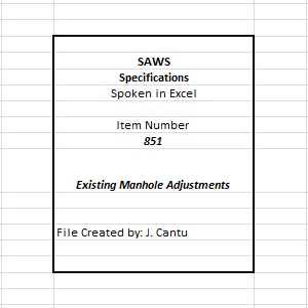16. At the direction of the inspector, all ungasketed mating surfaces shall be thoroughly sealed in accordance with manufacturer's recommendations with adhesive bitumastic products, see SAWS APL. 17. Where precast concrete risers are used, any gaps in the outer joint surfaces shall be additionally coated with quick-set, non-shrink grout. 18. Other construction requirements, refer to specification item number 852 sanitary sewer manholes for the following requirements.